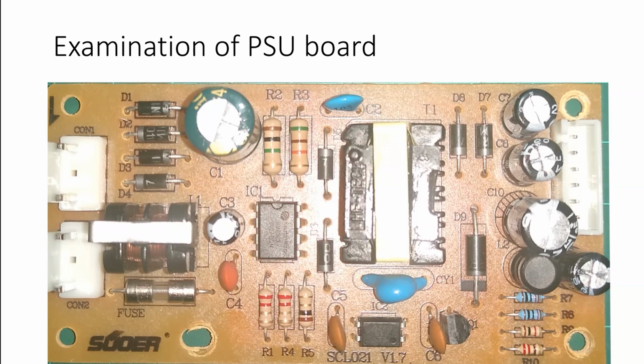There's then the 3 windings on the transformer, one for 5 volts, one for plus 12 volts, and one for minus 12 volts. And each of those has got its own single diode rectifier, just a simple half-wave rectifier. And then each of those has got its own smoothing capacitor. The biggest smoothing capacitor will be for the 5-volt line because that's beefier. And if you notice, the diode for the 5-volt line is beefier as well because it's supplying most current.